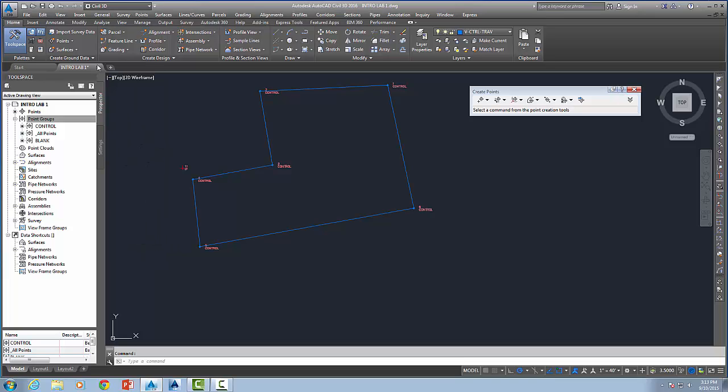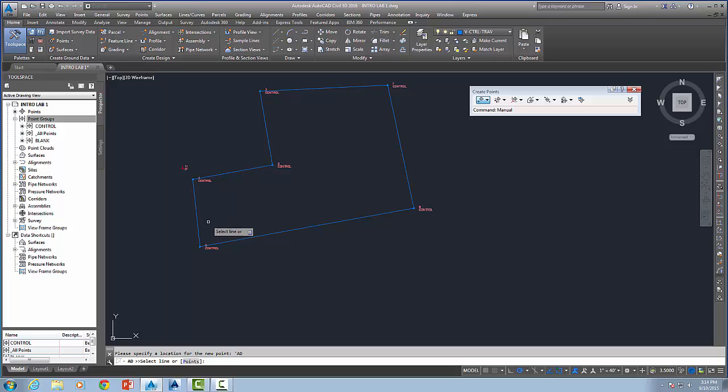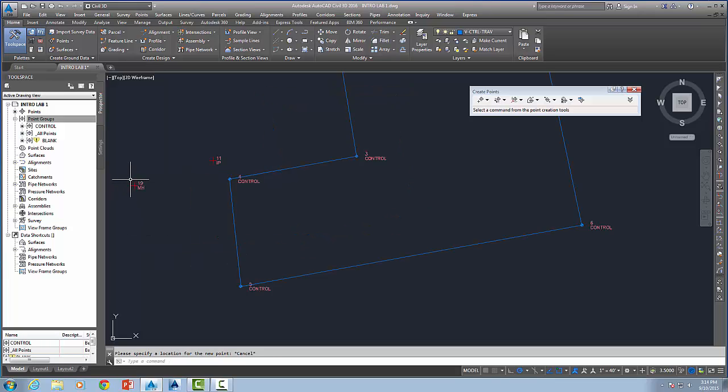So again, we're going to go ahead, create points by turned angle, select your line closest to 5, instrument setup and backsight looks correct, and this is again a negative angle, negative 39, 37, 36. Distance 188.24. Okay, point number is 19. This is going to represent for us a manhole, so I'm just going to put MH for manhole. And escape twice. What that does is allows me to then see that that point's in place.